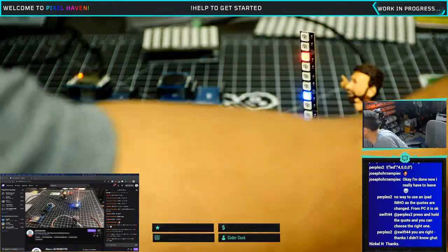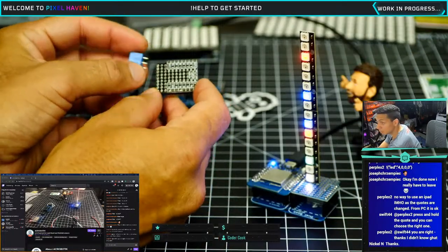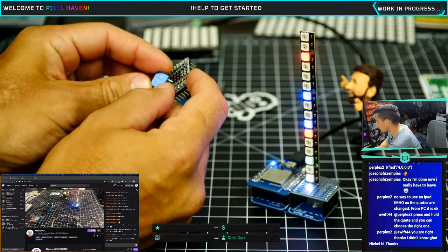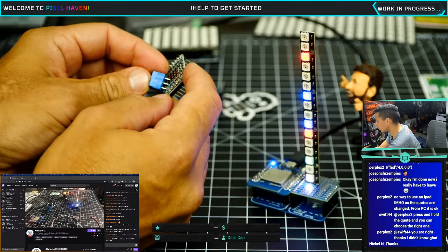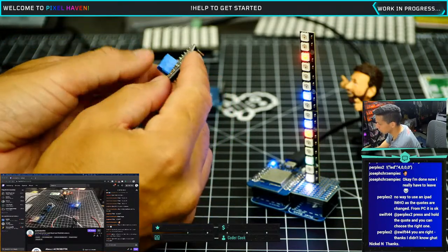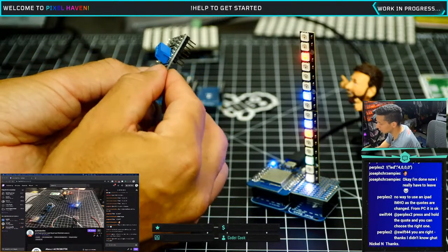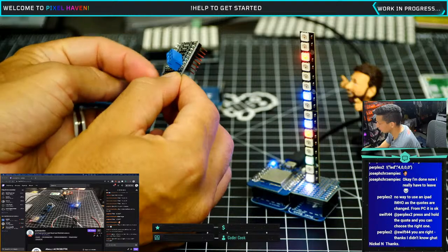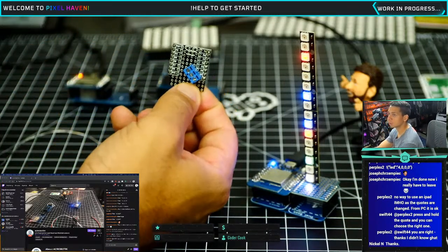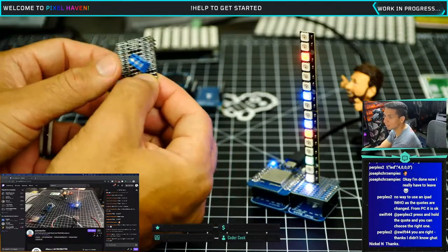And then, oh yes, some of you know the trick for this one, right? It's a 3.5 millimeter pitch for the block terminal, and it's 2.54 millimeters, right? Like a 10th of an inch on the actual proto board. So if you put the block terminal diagonally, it fits. So it's a nice little hack.